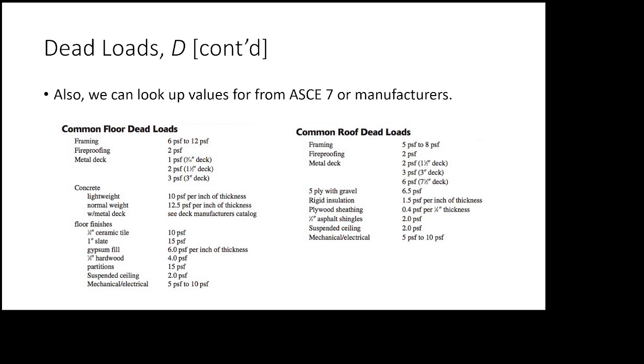How do you think I would determine the weight of this carpet, like pounds per square foot? Well, I can look it up in a guide like ASCE 7 because it has a lot of commonly available materials. What if carpet wasn't in ASCE 7? How would I determine the weight of this carpet? Say it again? Well, you could weigh it, but if you're designing, you haven't bought it yet. Call the manufacturer. Just ask them. Those are commonly available data points that a manufacturer would have available.